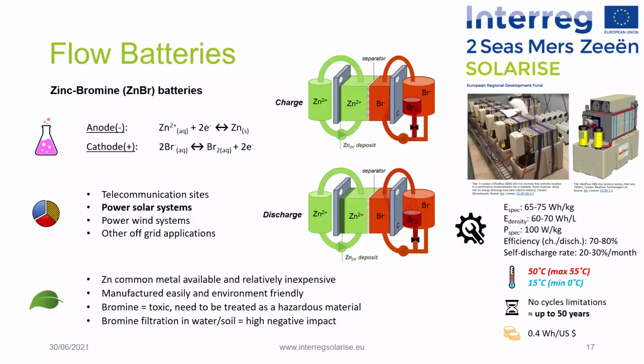The flow batteries are a type of rechargeable battery where the two chemical components of its chemical reaction are in liquid state and are pumped through the system on separate sides of a membrane. Ion exchange occurs across the membrane while the two liquids flow in their own respective spaces. Although they have technical advantage over conventional rechargeable batteries, such as potentially separable liquid tank and virtually unlimited longevity, current implementations are comparatively less powerful and require more sophisticated electronics. In general, it is important to remember that its energy capacity is a function of electrolyte volume and its power is a function of electrode area.